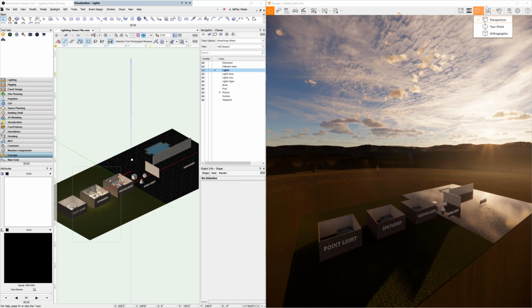Finally, then, the next couple tools over, we've got our navigation mode. Now, this tool, what it's going to do right now, we're flying around. That's what the wings stand for, but you could do the walk mode. So if we were on the ground and you didn't want people to be able to walk through walls or needed to go up and down stairs, things of that nature, the walk mode would do that for you.